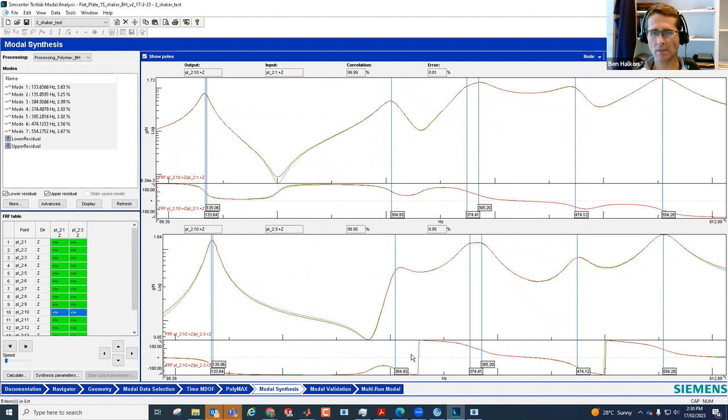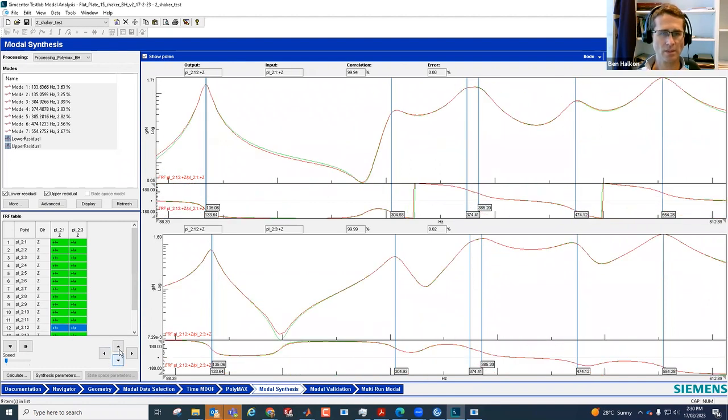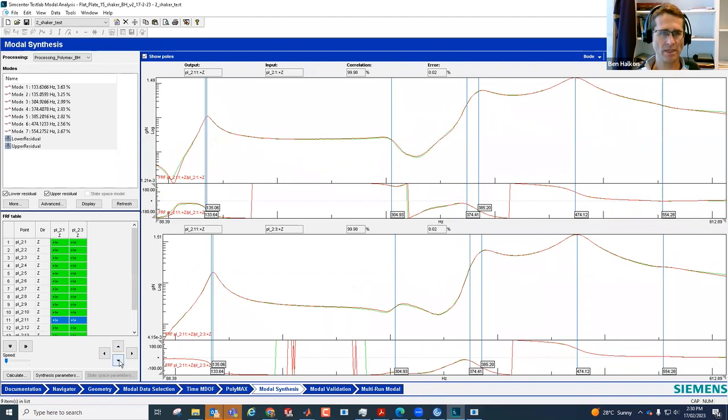Here you can see an example of a phase wrap. Another phase wrap here. You might have seen this from time to time as we've worked through these FRFs. This is just the phase wrapping through 2 pi radians. Phase can only take a value, of course, between minus pi and plus pi, but sometimes it will go lower than minus pi, which is essentially the same as being just under pi, and that's what a phase wrap is. We see a phase wrap if we pass through an anti-resonance or a resonance. So we work through these. Here's some more phase wraps.